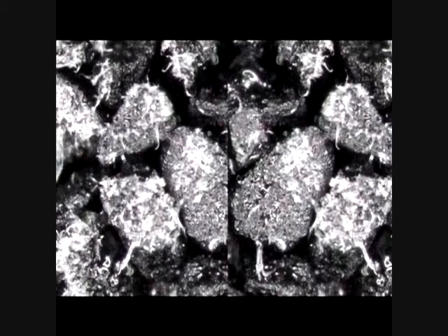A second competitive technology is an extruded carbon technology. The extrudate is actually an activated carbon matrix sandwiched between a top and a bottom non-woven outer scrim. The carbon granules are secured in place with an adhesive or a binder. It's a pretty good technology, but as can be seen in this image, the binder oftentimes is covered or occluded, and you should know by now what impact that can have on our performance.